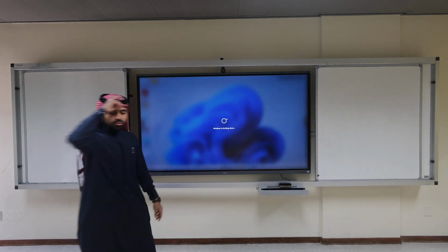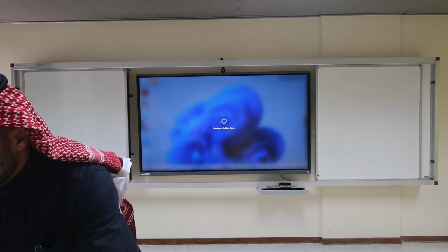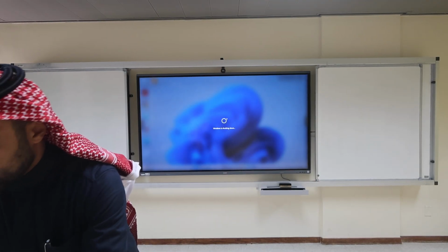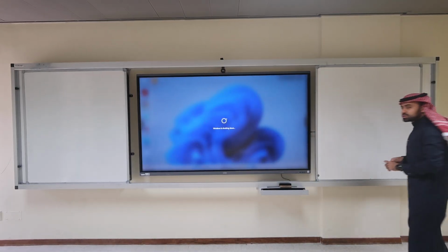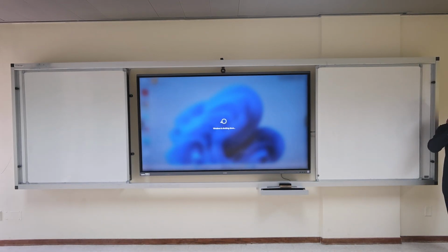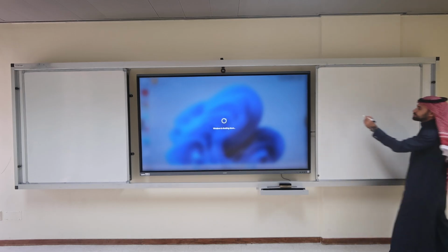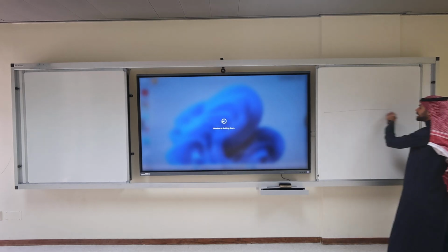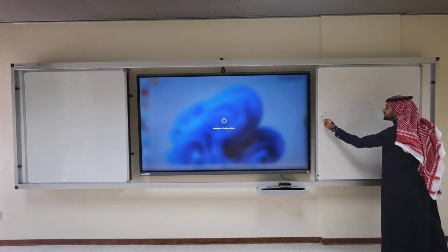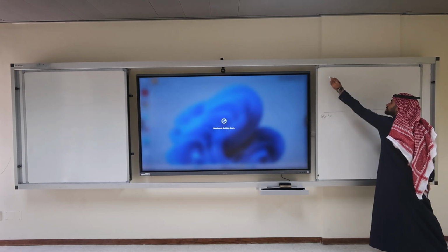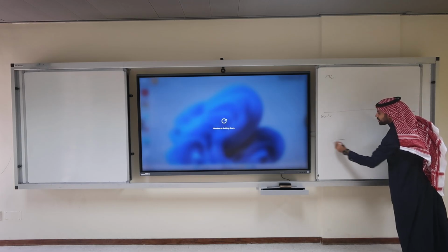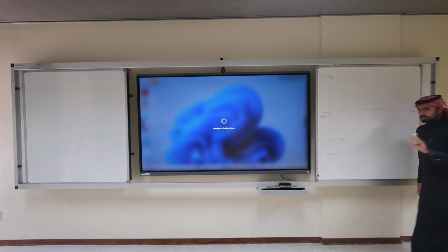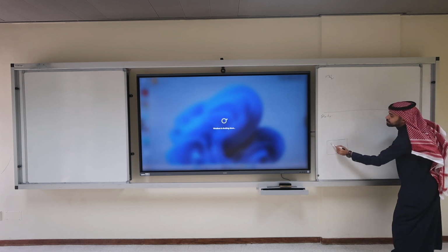Okay. So let me begin. Last time we talked about what? The exciter. And what did I tell you? Remember, in this course we do nothing but block diagrams. They're very important. In the exciter, we had here the stator, and here the rotor. So the first step is to apply a small 3-phase, not the pilot, the regular one, small AC. 3-phase AC.